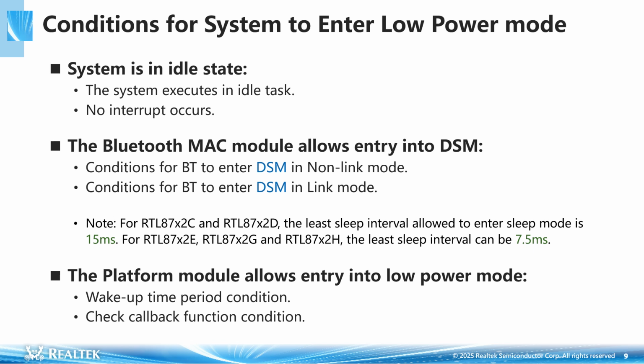Third, the platform module allows entry into low power mode. This requires meeting two conditions. The wake-up time period must be within acceptable limits. Generally, it should be larger than 1 OS tick, and the check callback function must return a pass value.